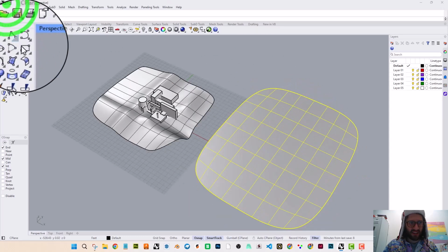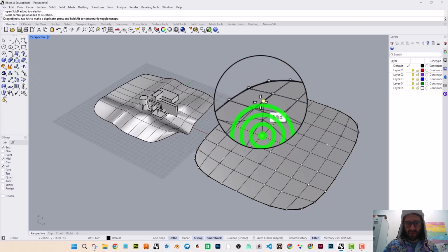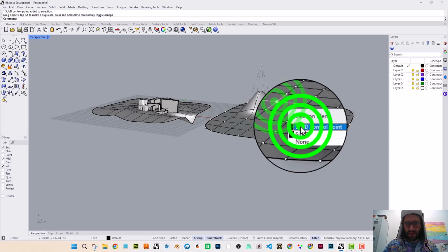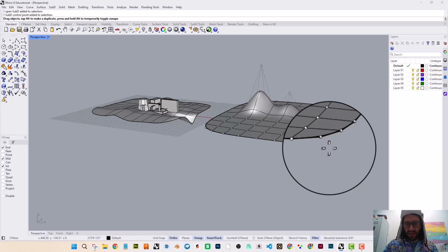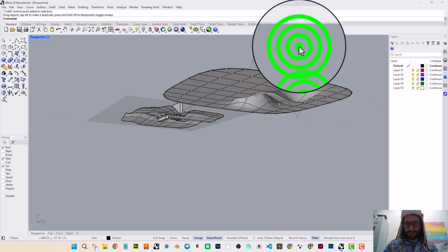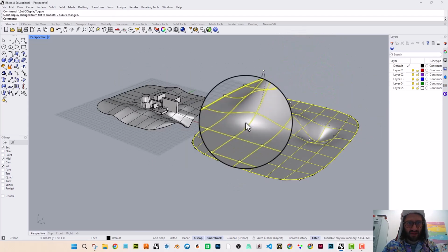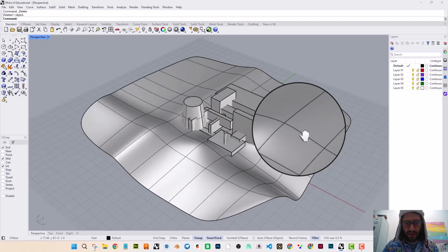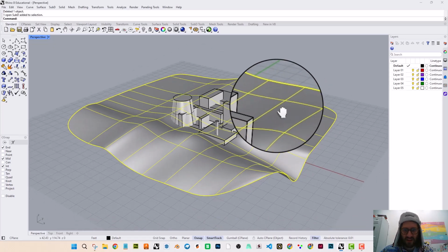Went back over to standard, and that turned on control points, and then I could click on these points and move them up and down in order to make some topography as a big surface or whatever. I already did that. Oh yeah, and if you hit tab, it switches between these two views, but I can delete that. There's different ways you can show topography in your drawings.